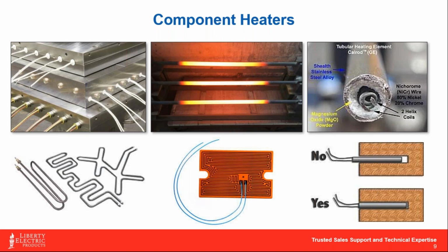What I do think is a pretty interesting factoid is many times those resistance wires are as thin as 37 gauge, which, to put that in perspective, is about a third of the size or diameter of dental floss. So it's really thin stuff, and you can hit it with 480 volt, even 600 volt, and it holds up for years. So I've always been pretty impressed by that.